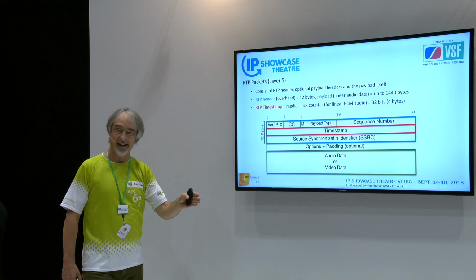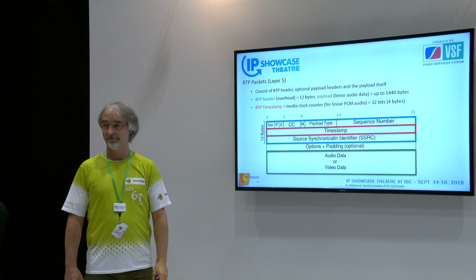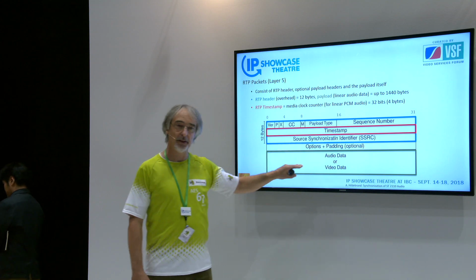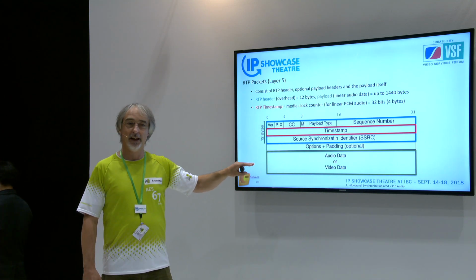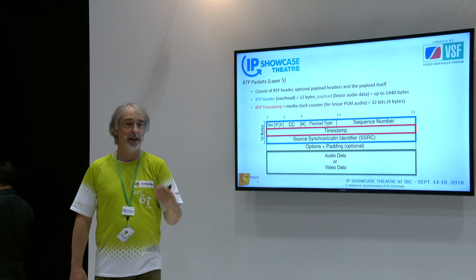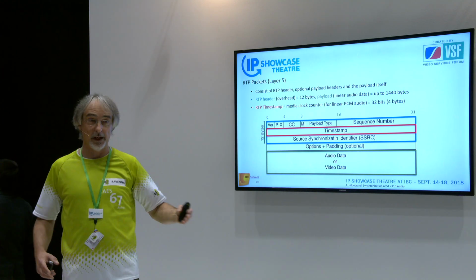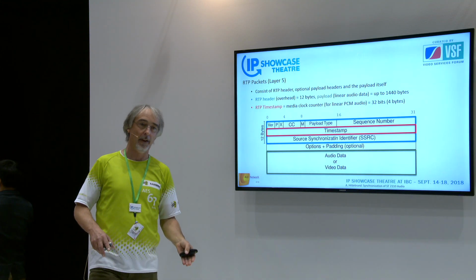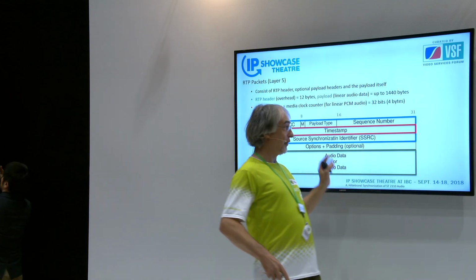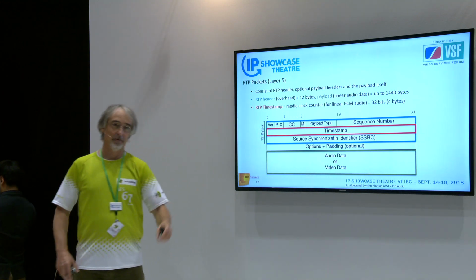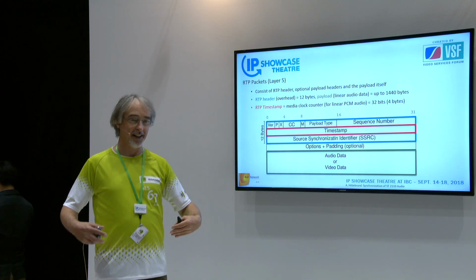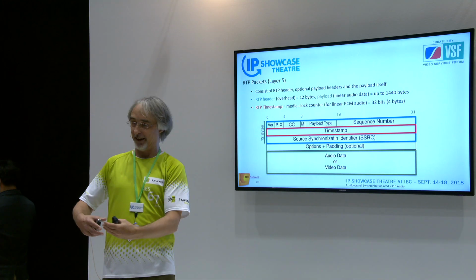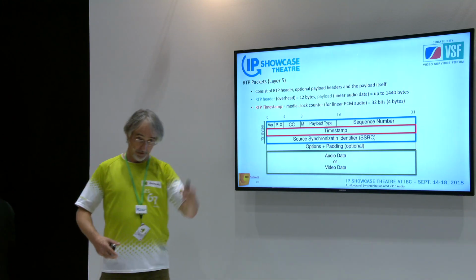What was the media clock count when that sample had been generated? So basically we have the media clock count for that particular first sample in that packet, looking at it as if the stream had been instantiated on the 1st January of 1970, because that's the time origin of PTP. Of course, the clock count advances, and with 32 bits, you can see we have rollovers once per day. But since we know the exact time of day, we can easily calculate modulo 32 where we are exactly with respect to the day.